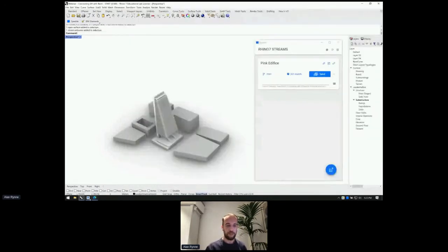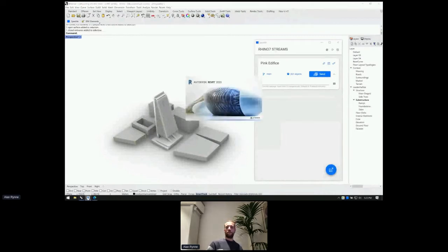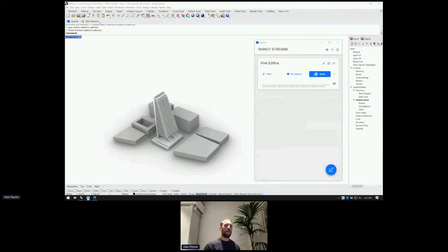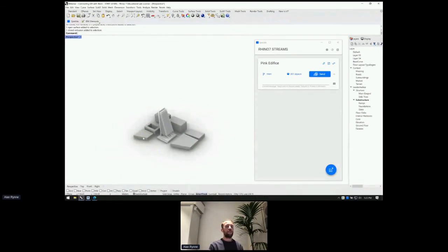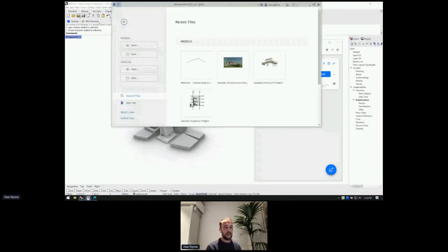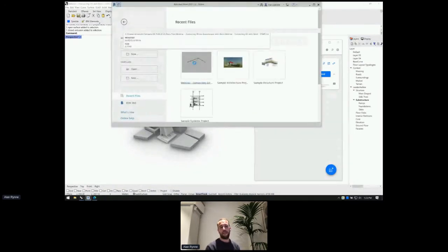Okay, so while that happens, since we need to wait for another minute, basically what is going to happen when we receive that data in Revit is that since we haven't actually provided any information of what we want each of these objects to be, we make no assumptions, and they're all going to end up being generic models. And if you understand a little bit of the object structure in Revit, specifically they're going to be direct shapes with a generic model category. So we make absolutely no assumptions, and you get the most generic element ever. Let's see if we can manage to do that.